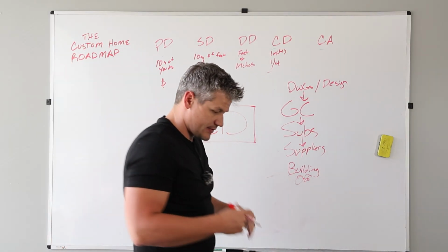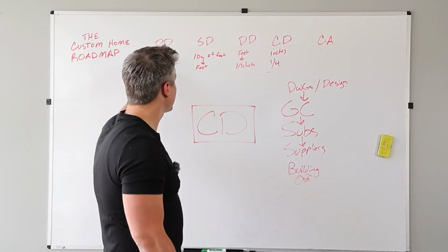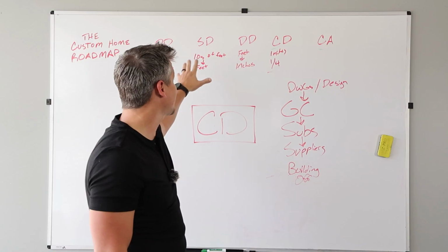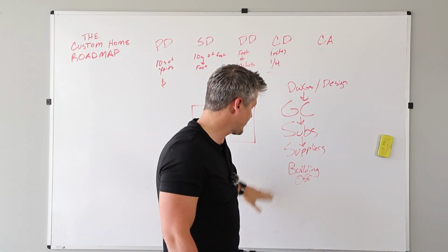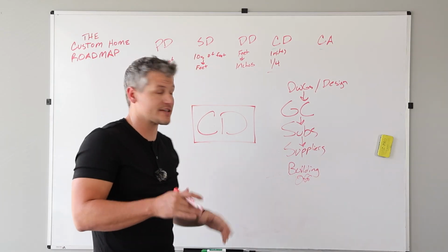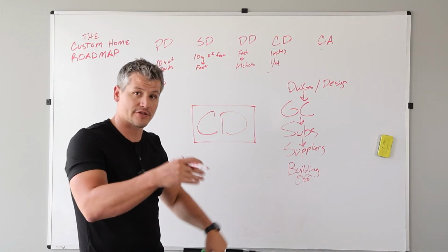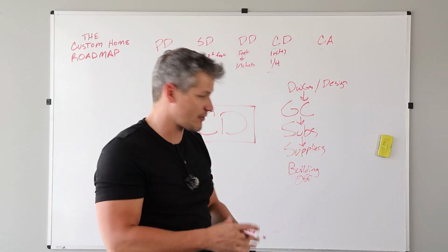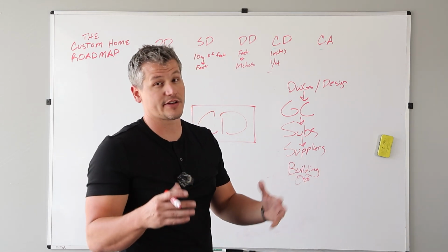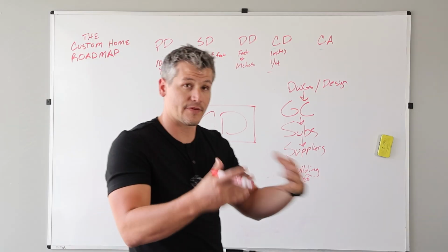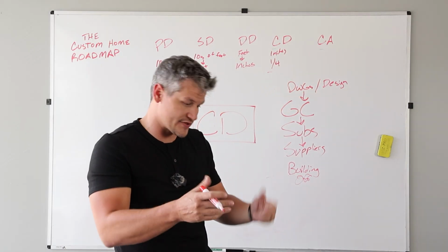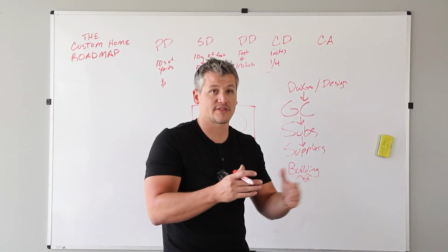That's a really important point. That's why we were talking about zoning so early in the process, because we've started to hang our hat on that information as we're going through, and really the building officials are just checking that at the end. Sometimes in pre-design or schematic design, I'll actually reach out to the building officials to make sure that I'm interpreting that zoning correctly. But just know that the building official needs to understand that we're meeting those height regulations, or that area. If you can't build above a certain area, they need to have that on a piece of paper with a stamp that says, yes, this is going to work, or this is in compliance with that zoning.